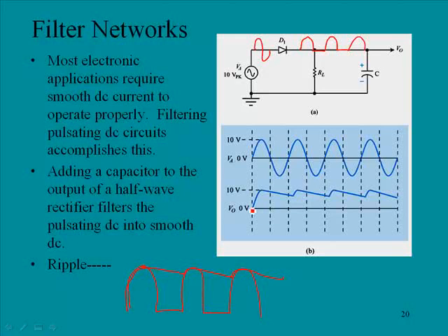And so the original signal would look kind of like this, and like this, and like this, and like this, but the resultant is something that looks kind of like this, and the value you're seeing here is a bit exaggerated. Actually, it can get quite smooth depending on the size of the capacitor, and some circuits will utilize several capacitors. But this resultant value, this value that you see changing slightly, is referred to as the ripple.